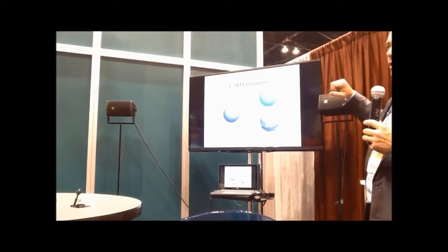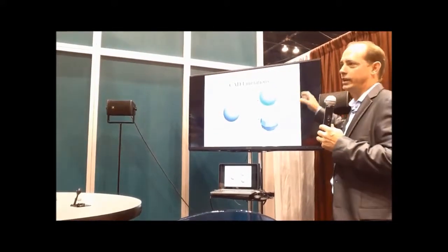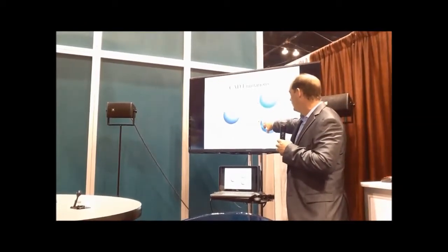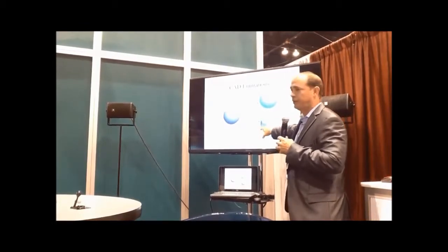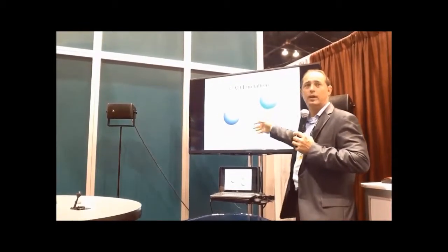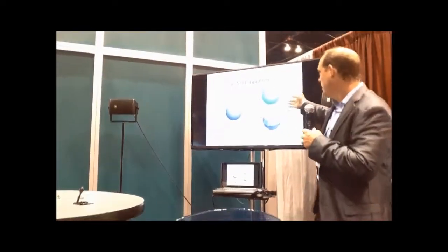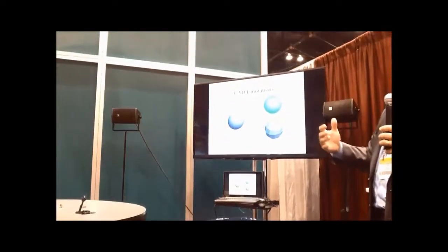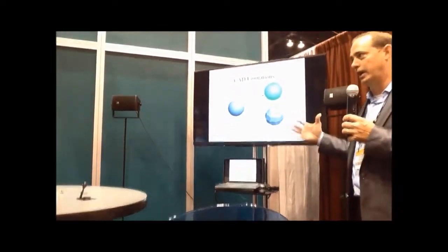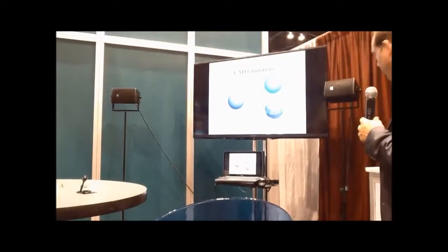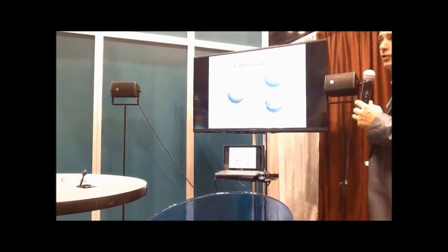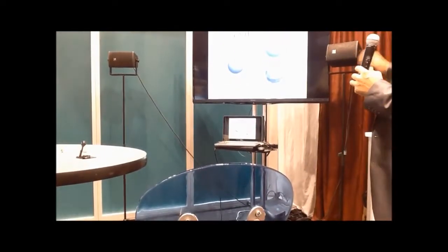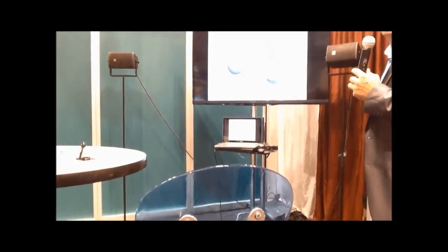Now, you may hear people say that your file's tessellated, or it's triangulated, or it's not tessellated enough. What they're trying to refer to is these triangles that you've got here. You can break any of these into more and more triangles. The more triangles you get, the closer representation you have to the actual part that you're trying to produce. So if they say that your file is tessellated, it means that it doesn't have enough triangles in it. The objective is to try and get that to the point where it matches what the machine can actually produce. Because you can make a tessellated file that's way over the size that any of these machines could produce in resolution.